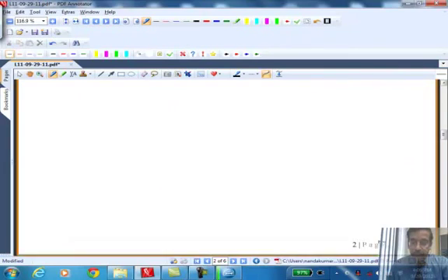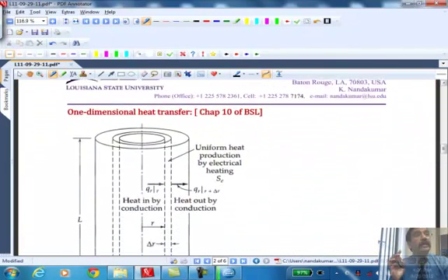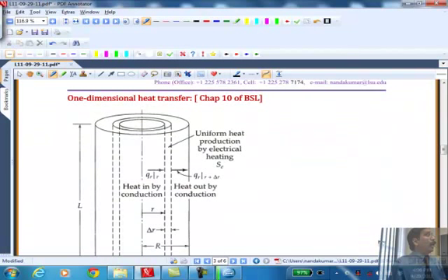Okay, so we have seen so far one-dimensional problems. That is one velocity component that is changing in only one spatial dimension, plus time also. Okay, both steady and transient problems. Couette flow, Poiseuille flow, in plates, in cylindrical pipes, concentric cylindrical pipes with angular velocity or with axial velocity. All these combinations you should be able to handle.